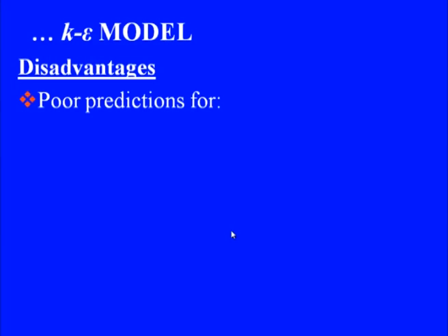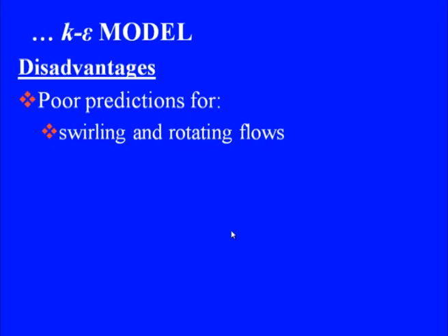There are some disadvantages though, which are linked basically to the way we had assumed a scalar eddy viscosity. So, it provides poor prediction for swirling and rotating flows, wherein the scalar eddy viscosity assumption does not work very well. Similarly, for flows with strong separation, axisymmetric jets, certain unconfined flows and fully developed flows in non-circular ducts.